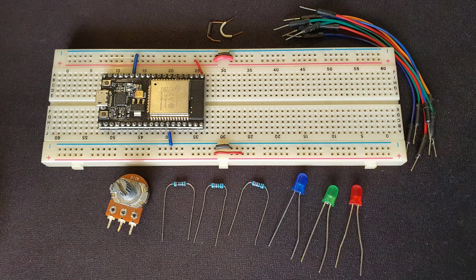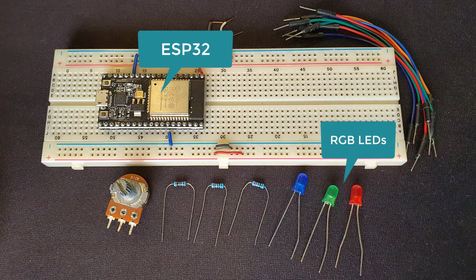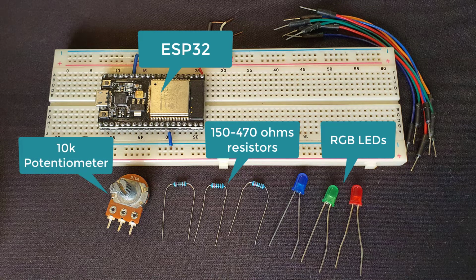For this experiment, you'll need the following materials: your ESP32 development board, 3 LEDs, red, green, and blue, 3 current limiting resistors. Values could range from 150 ohms to 470 ohms, a strong magnet, 10 kilo ohm potentiometer, a couple of connecting wires, breadboard, and a micro USB data cable.